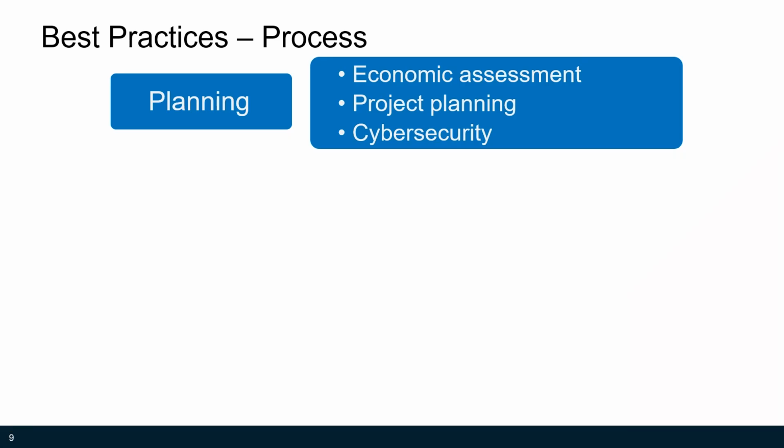In the planning phase, an economic assessment helps determine the viability of the project by comparing it against alternatives. For HVAC integration projects, a lifecycle cost analysis may be a better representation of the project's value, as opposed to a simple payback analysis. A preliminary planning exercise can reduce challenges later in the process. Planning should include ensuring compatibility for systems integration and evaluating existing controls.